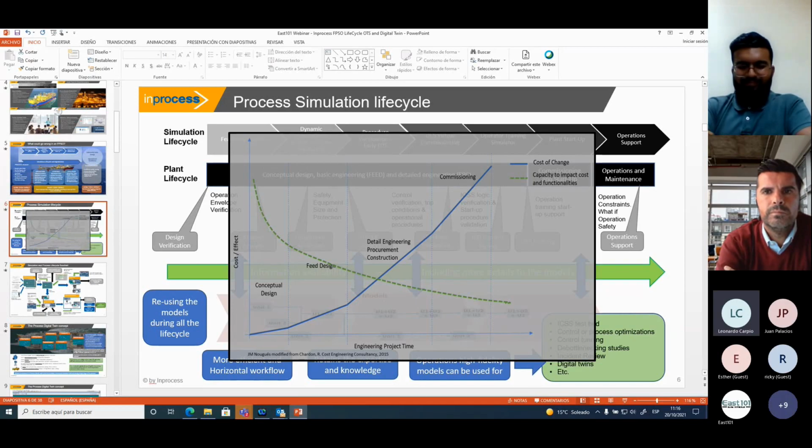The other point is basically how big is the plant, right? If this is a massive plant, maybe just with one model it isn't sufficient. And then in this case, you need to split up the dynamic model, for example, in two. And then you need to understand very well at what point is the more efficient place to cut the dynamic model in order to improve the computational time without breaking many interactions within the systems, right? These are the two main points, right?